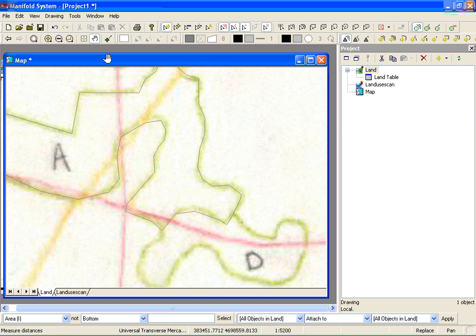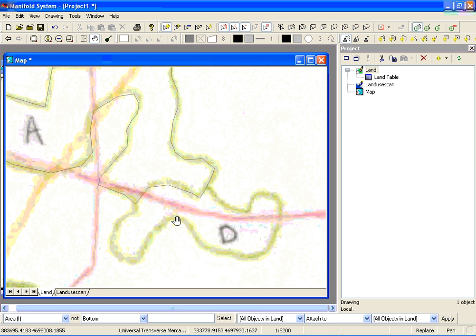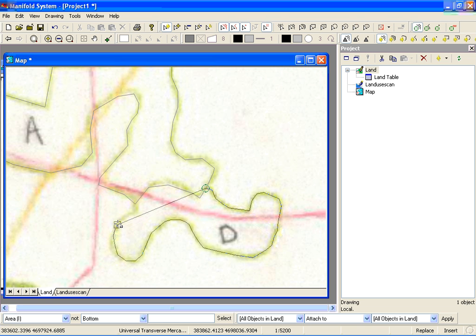Let's zoom out and do another polygon. Let's try this developed one right next to it. Now I'm going to add another polygon, but here I'm clicking on the snapping tool. And when I do that, I can snap on an individual line by hitting the space bar. And this is called Snap to Areas. Now after I click on my first polygon, I can hit the space bar again, and that way I'm no longer running in the snap mode. So I can continue to click on my left mouse button.